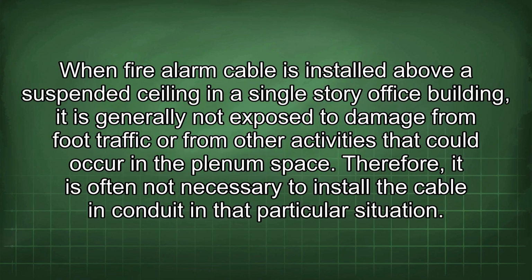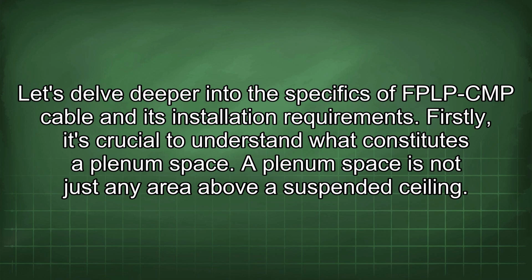When fire alarm cable is installed above a suspended ceiling in a single-story office building, it is generally not exposed to damage from foot traffic or from other activities that could occur in a plenum space. Therefore, it is often not necessary to install the cable in conduit in that particular situation. Let's delve deeper into the specifics of FPLP CMP cable and its installation requirements.